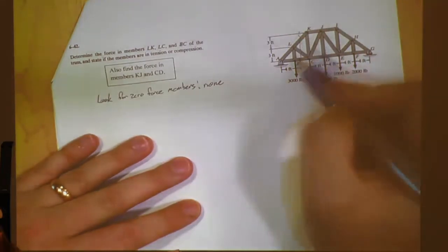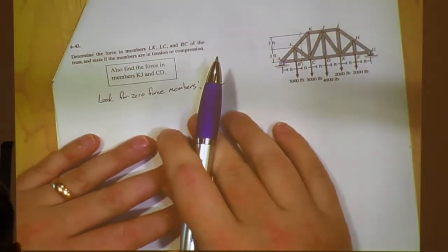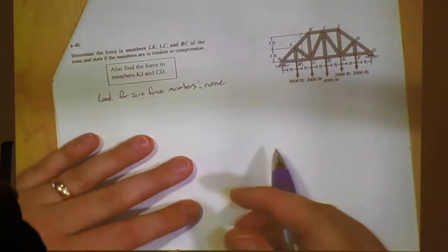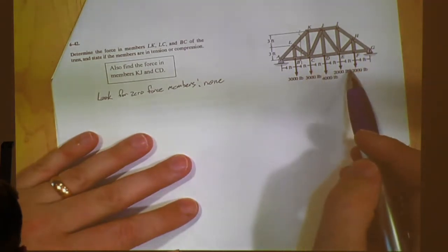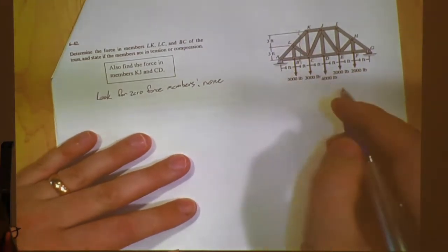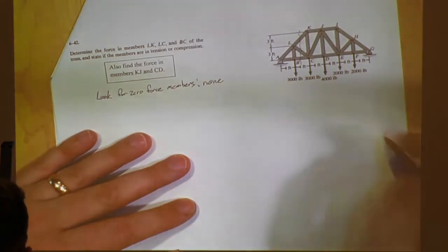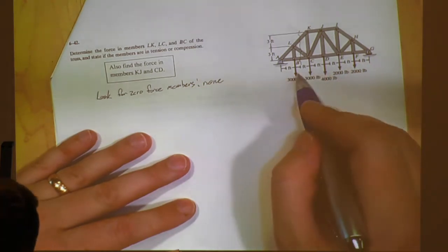You can either cut it here and incorporate all of the right or incorporate all the left. Why would we want to do the left? There's just less to calculate. We don't have to take into account all these forces in order to get there. Because if we do method of sections, we have to incorporate a moment, right? So doing a moment for these four, or we just do the moment for the one.